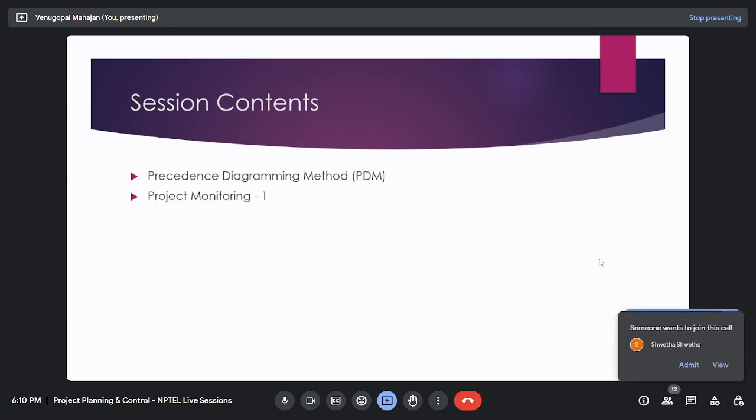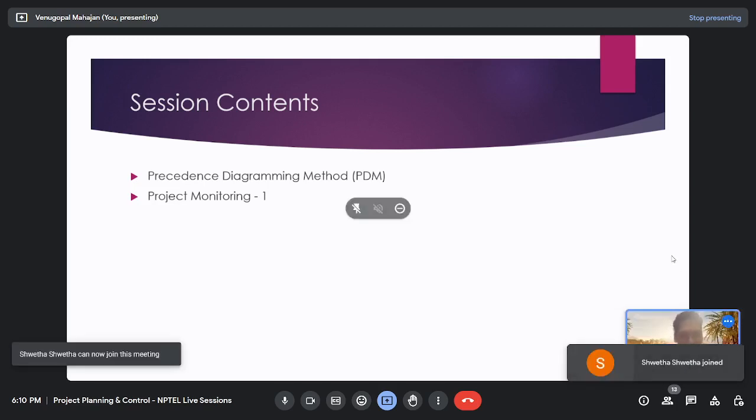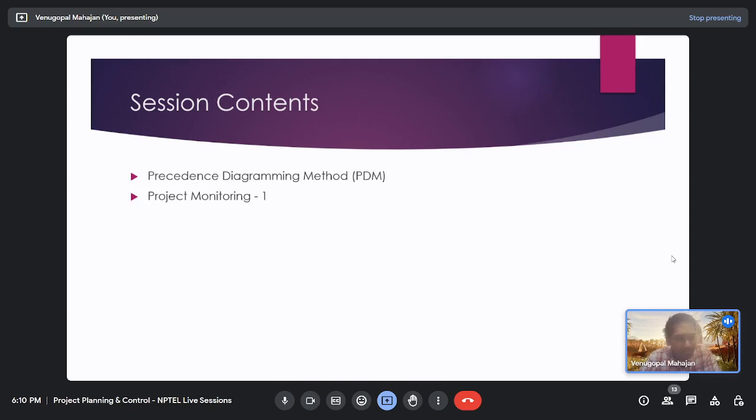Like in last session, we did one numerical where if you just go by CPM, your duration came out to be 10 days, but by limiting the resources to 10 only, the project duration extended to 14 days. So it does happen, and it also happens in our numericals when we have allocation problems. But leveling problems, no. Leveling, we deal with constrained project duration.